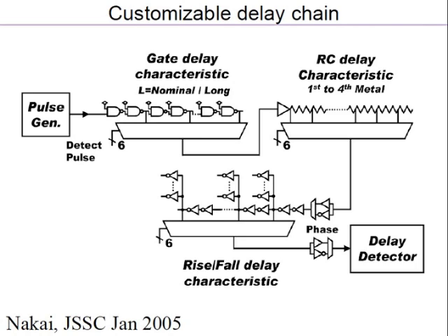So like that you can get that frequency to voltage curve of the chip. That is called the Schmoo plot. But you don't know within the chip which portion has failed. You know it has failed at that frequency, but you don't know which portion. To get that information, you need additional circuitry inside the chip, and that requires additional circuitry to be put in.